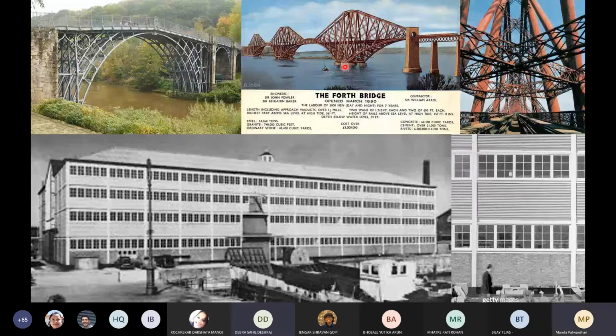Then this is the Forth Bridge. This is called the Forth Bridge. I have an enlarged image here just to explain to you what these members look like close up. Okay. So this is a kind of complicated assembly of these members. These are tubular trusses. Okay. So these members are all tubular, circular, hollow, right? The tubular members have been put together to get these kind of cantilevered trusses.